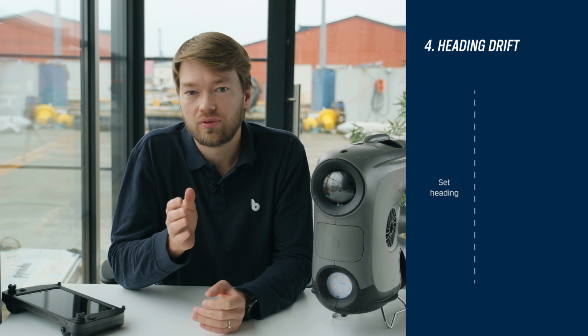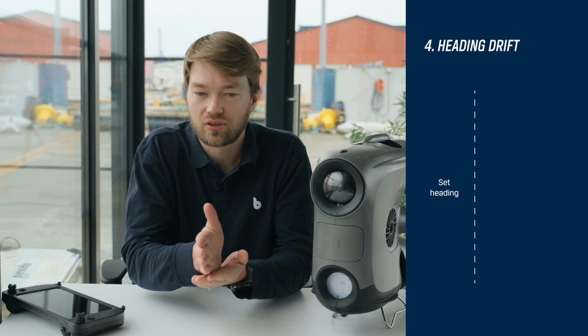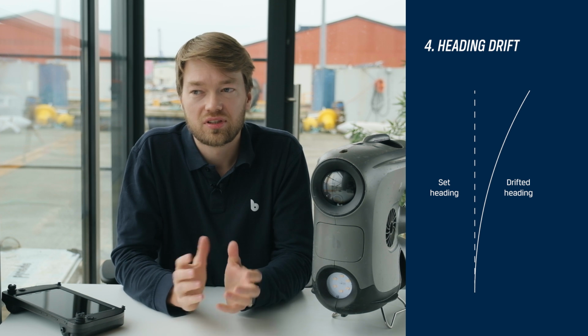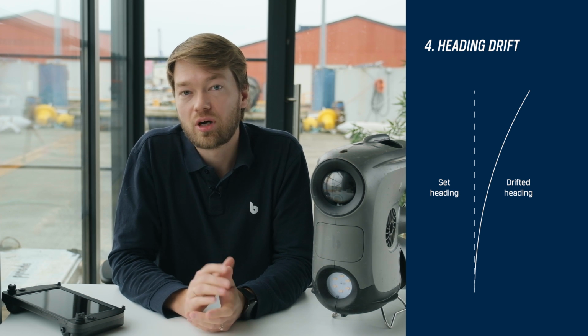The fourth component is what we call the heading drift. The heading drift will typically start curving the position off instead of going in a straight line. So this is typically the dominating component as time goes by. We really want to minimize all these 4 components as much as possible to get the best possible position estimate. Now I will show you how to do this in the app, but before that we have to put the drone in the water.